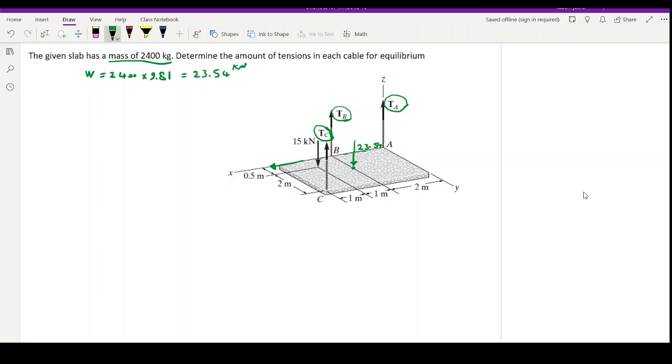That being said, you have to look at the given forces and the configuration of the given forces and see by taking moment about any point or any axis, you can eliminate some of the unknown forces and find one unknown force from there. So I start with taking moment about x-axis, and I assume that counterclockwise is positive direction.